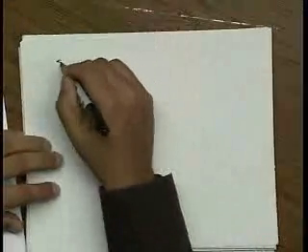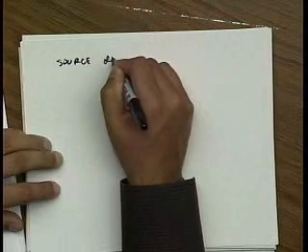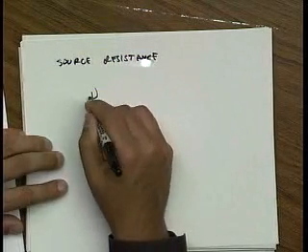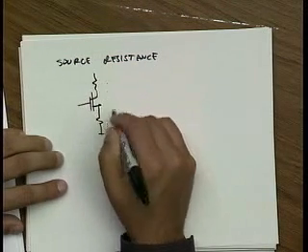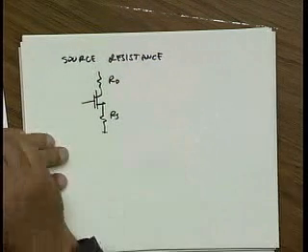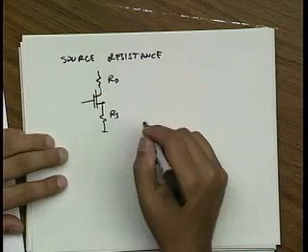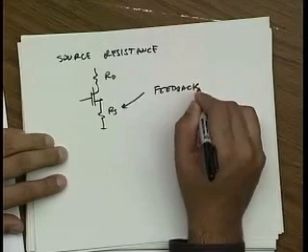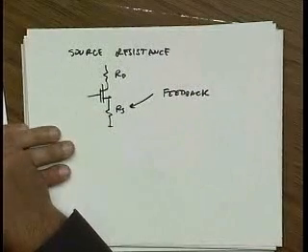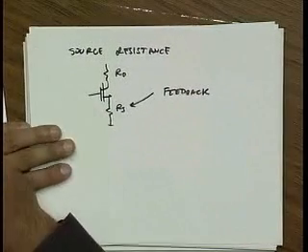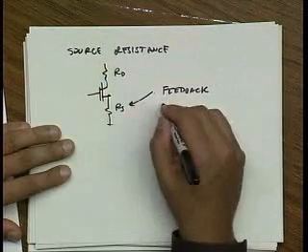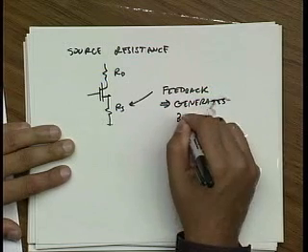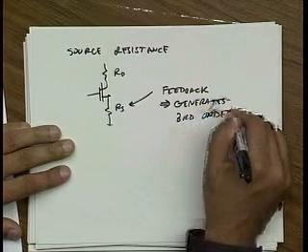Let me talk a little bit about source resistance. If I look at my FET, I always have a source and a drain resistor. And what we'll show next lecture is this is a feedback mechanism. You say feedback is good, right? It should reduce the distortion. It does, but unfortunately it also generates third order. Okay, we'll see that next lecture.